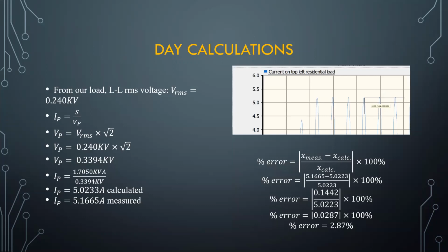Since the demand is not constant, during peak hours, peaking power plants gradually come on and provide extra power that is needed. Natural gas power plants are an example of peaking power plants since they have a faster startup time compared to coal plants. The downside of this faster startup is that it has higher fuel cost. Typically, coal plants can take 12 or more hours to start, which makes them good to satisfy the baseload demand, and is why we chose the coal plant for our source.